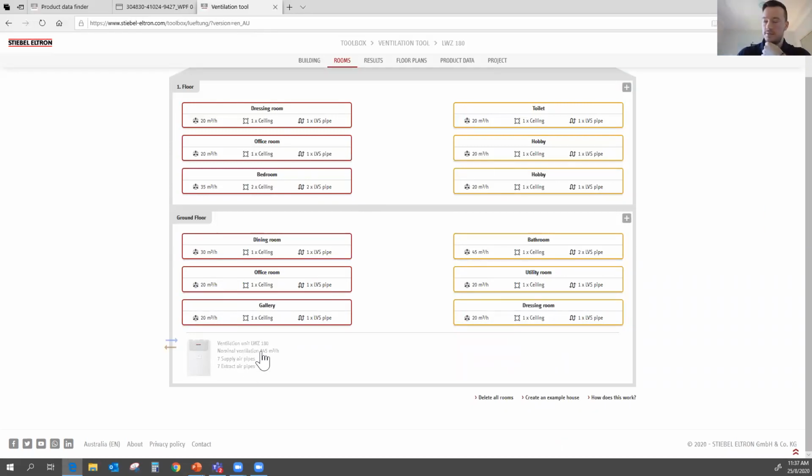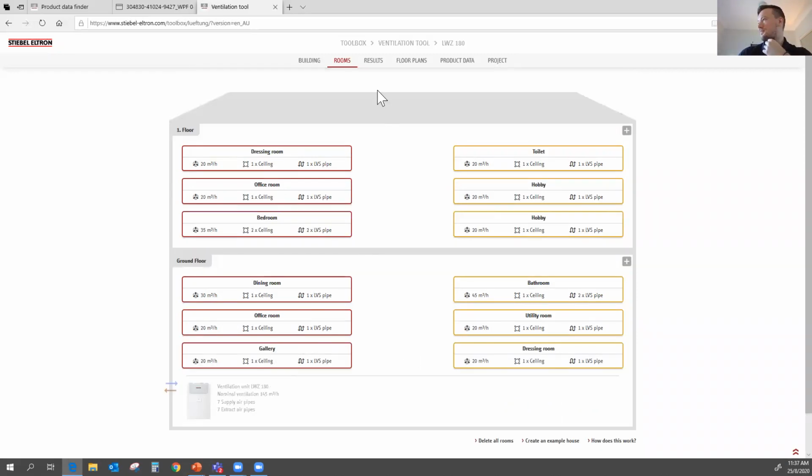And then we have an intensive ventilation stage that's one up from here, which can be triggered, for example, if people are showering or there's more people in the house. And that's usually 30% on top of this number. So we make sure that that's within the range of what the ventilation unit is capable of doing without maxing out the fan too much.